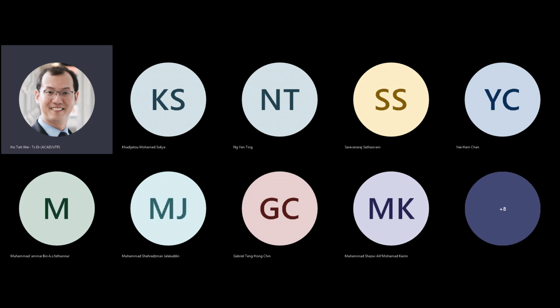So this synchronization mechanism of the D flip-flops actually makes it easier to analyze what the limitations of the circuit are. Why? Because you'll have a whole bunch of combinational logic blocks being synchronized by D flip-flops.